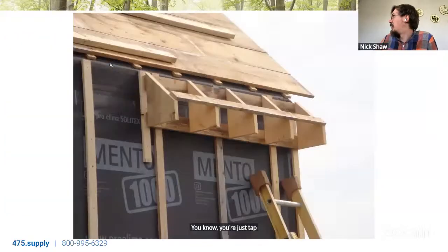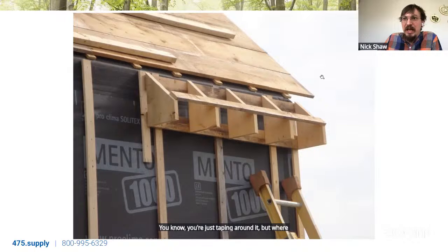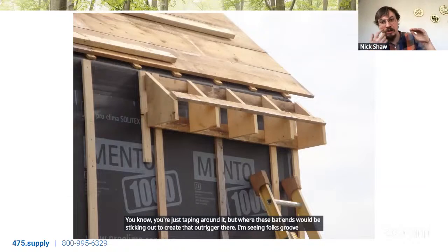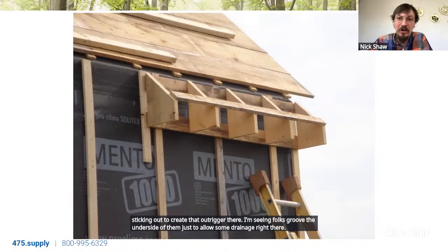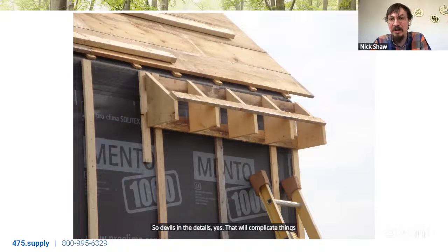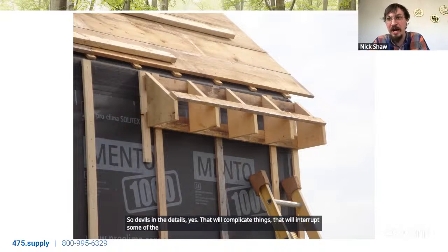But where these bat ends would be sticking out to create that outrigger there, I'm seeing folks groove the underside of them just to allow some drainage right there. So devil's in the details. Yes, that will complicate things. That will interrupt some of the venting and drainage right there.